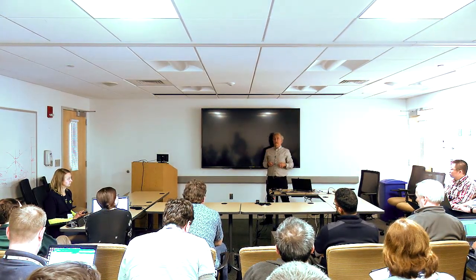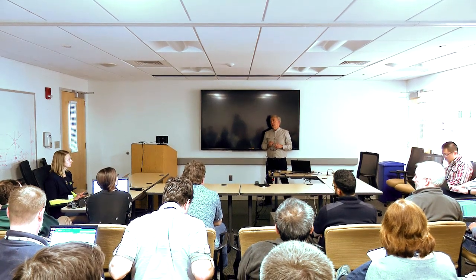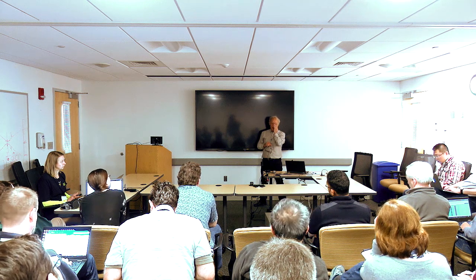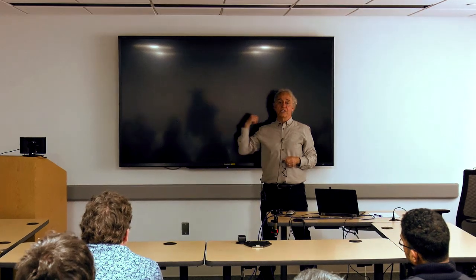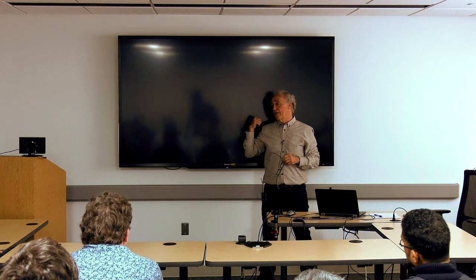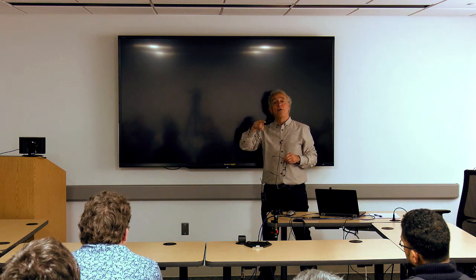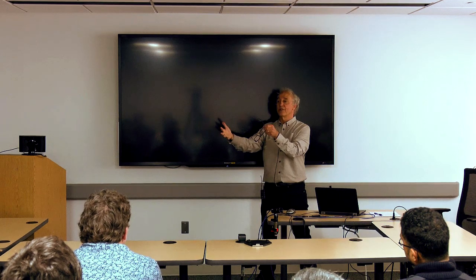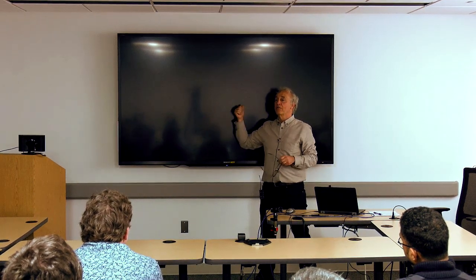Any more questions? Why would you want to use channel access instead of PV access? Because there are a lot more clients right now that know channel access than that know PV access. There are also some channel access client tools that are, in my opinion, richer. Even caget: if you want to caget an area detector waveform record, you can say caget -# 100 and just get the first 100 elements of the array, but there's no equivalent in pvget.